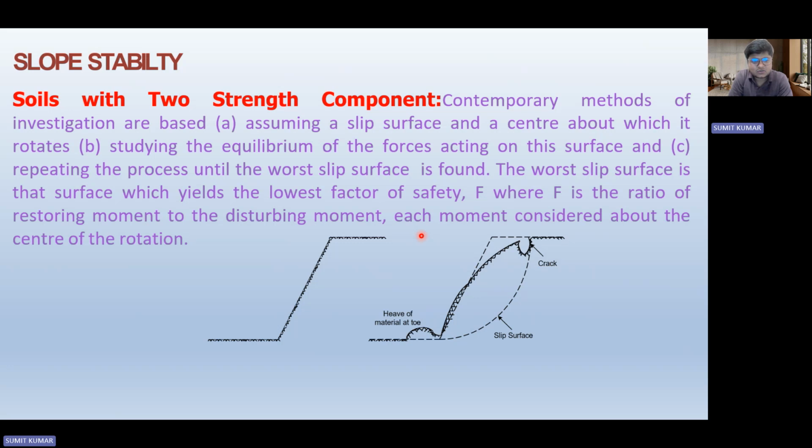After identifying the worst slip surface, the factor of safety is calculated, and we could state this much of the factor of safety, as we have identified all the critical slip surfaces which could be possible at that specific site. It becomes necessary as well as sufficient.